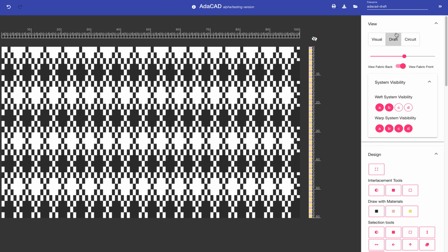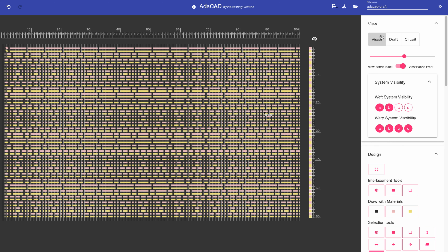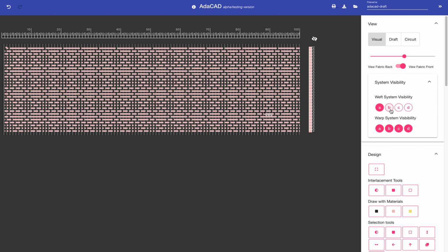If I were actually going to weave this, what I'd be weaving is an entire patch of one continuous conductive yarn that goes back and forth and back and forth. This entire patch, you could measure it, is a force sensor. But let's say we want to make this a little more elegant and we just want our force sensor to be in the middle of the patch. Well, then we can actually just go back.